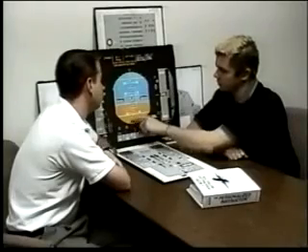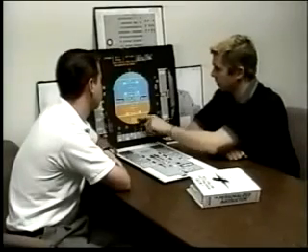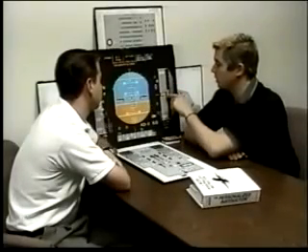Is there any other time that the numerical value might go amber? Yeah, it's similar to the whole decision height and problem down here. When you descend below an MDA that's set in the MCDU, these will turn amber.